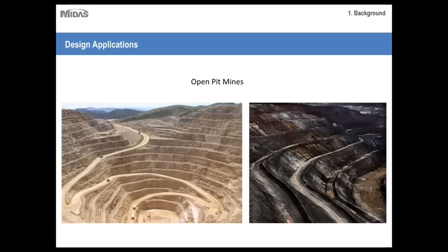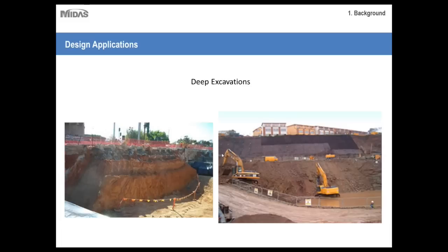Also, dewatering bores may be used to relieve water pressure by drilling horizontally into these walls, since water pressure is often enough to cause failures in the wall by itself. So even though rock slopes are naturally much more stable than soil slopes, there's still various things to consider, and there are still instances when structural reinforcements might be needed, especially for open pit mines, which consist of several layers of slopes.